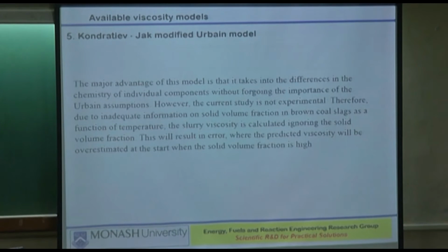So if solids fraction is high, then it will be very viscous. So they will not tend to flow. So they will be overestimating the actual viscosity. So the point is, which you also tried to make, 1450 is the melting point temperature given by the database and other sources. But the database doesn't tell you how long you have to keep it at 1450 before it becomes fully liquid.